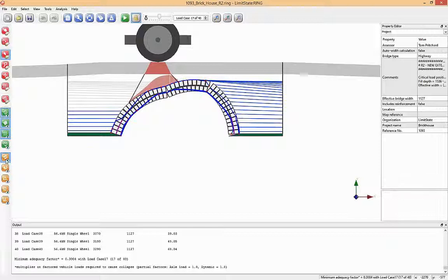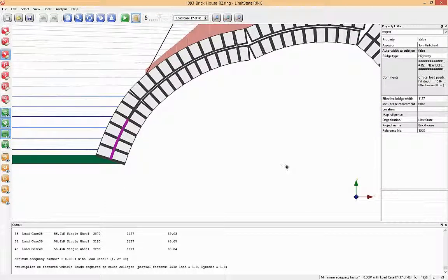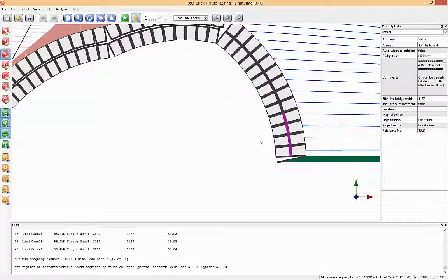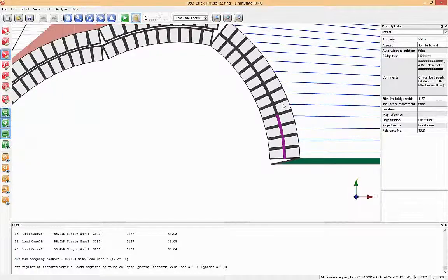What I'll do is I'll just again zoom in so you can see clearly where the ring separation has been prescribed. So it's prescribed where the inter-ring joint is black, and we have effectively glued together the inter-ring joint where we have this purple colour.